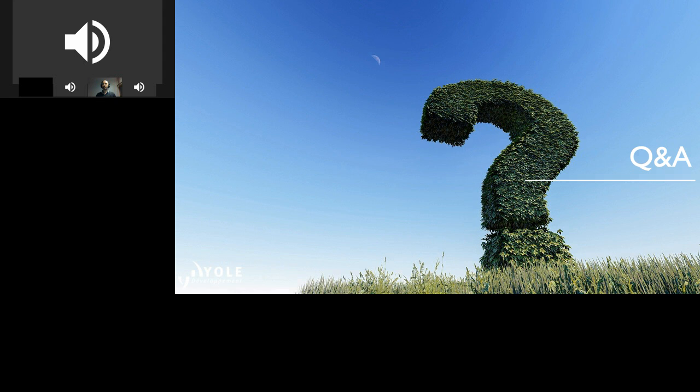Well, that's a good question. Yes, it is possible to use just a single module for two different materials. Obviously, we need to match the process temperature, but out of the list I showed for high and low index materials, we can always find a combination of high and low index material deposited at the same temperature, hence allowing just one module for that. So yeah, that's possible.